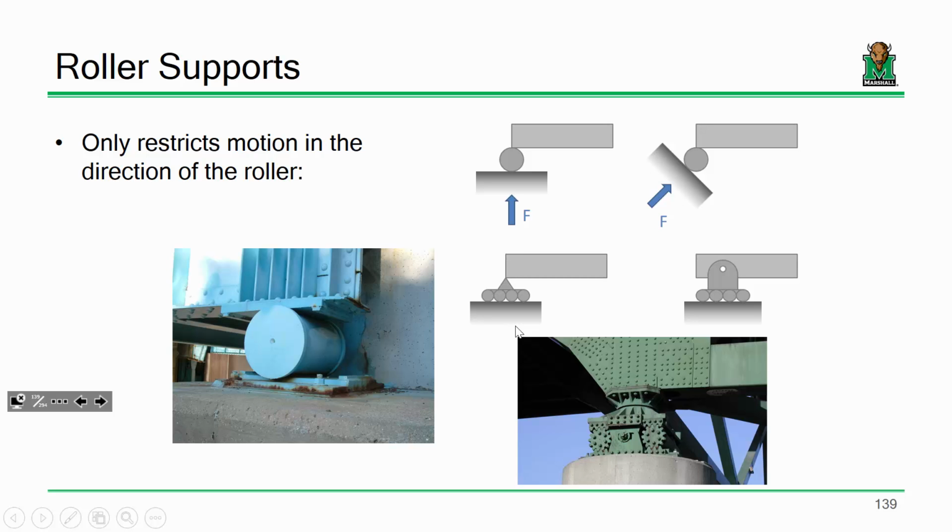You see stuff like this a lot in, let's say, bridge systems. You might not see a literal cylindrical wheel on the bridge, but you might see something like the difference between a fixed bearing and an expansion bearing. So the idea behind that, and this actually relates to something we've talked about earlier, let's take a bridge in, let's say, West Virginia. Our summers can get to, like, 95 degrees fairly easily, and our winters can go below zero, right? So what's going to happen to that bridge throughout its life? It's going to expand and contract, right?